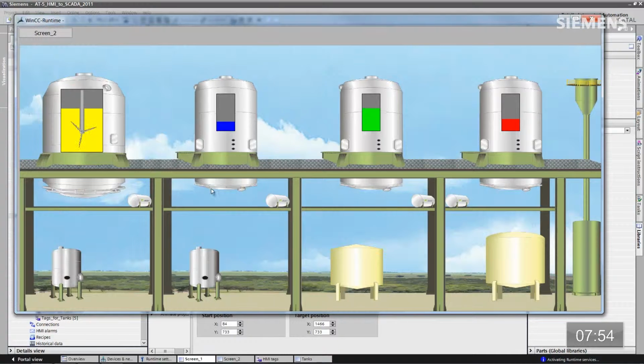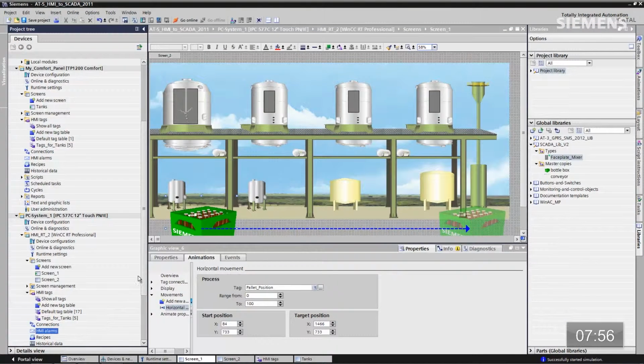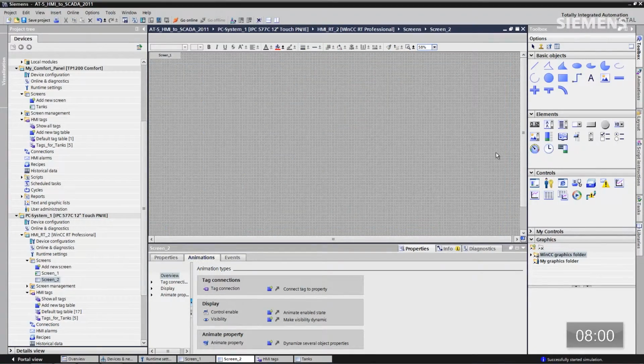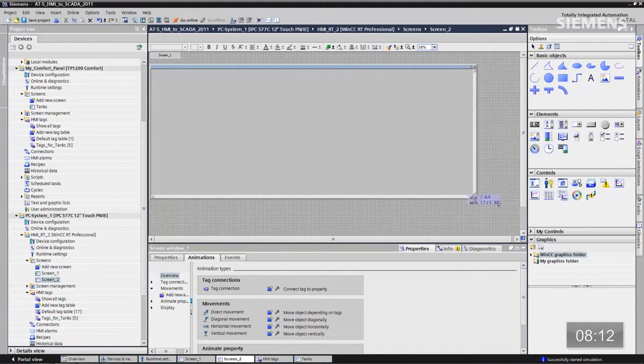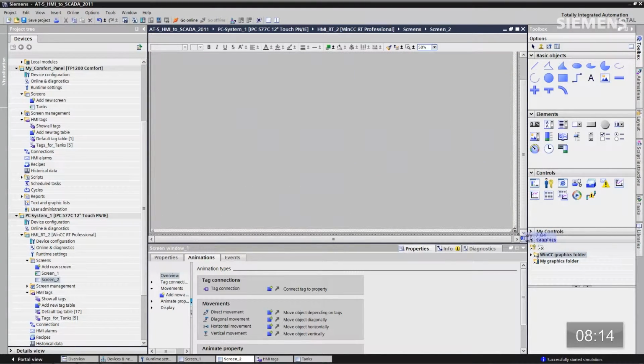However, there's one other thing I want to show you. How about actually doing a screen-in-screen or pop-up technology? So let's go to screen 2 real quick. Double click on him. And let's go grab the control icon for this. It's called Screen Window. Let's drag it on. This is an ActiveX control. You can see a little alignment bars just like in PowerPoint. That way you can align your boxes wherever you want to and get everything sized right. Let's resize, refit them on to the screen.